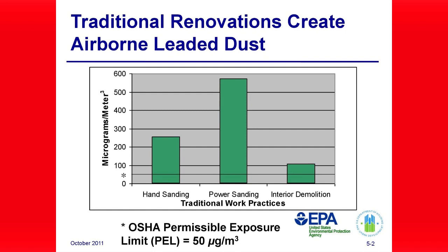By using safe work practices, you can control and significantly reduce the amount of dust created on the job. Controlling leaded dust at the source of generation is important because dust released into the air will eventually become settled dust on the ground.